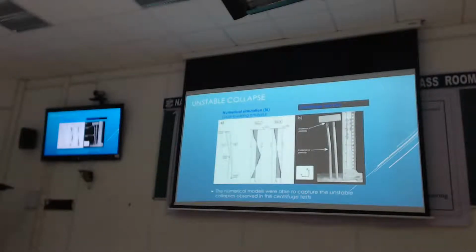Okay. Now we have a numerical solution and procedure. We can look at what the numerical solution tells us in terms of bending moment and where the plastic hinges should form, and compare them to what actually happened. So the bending moments plotted from the numerical analysis are here. You've got a negative peak, a positive peak there, and this is quite a big peak, so there should be a plastic hinge there, and here only it triggers a hinge there. So we think the hinge is somewhere here, one there, one there. So it's a 3-pin mechanism that's allowed to form here.